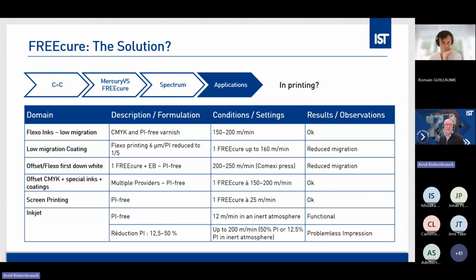But basically, we found that when we use an inerted atmosphere and reduce the photoinitiator content, which is pretty high in inkjet formulations, to 50%, we were able to print almost every inkjet ink in the market with satisfactory results with only half of the initiators. And that has been just the beginning. In reformulating and using additional mechanisms like an amine modification, our partners have been able to reduce the photoinitiator content down to 12% and even lower. And that is a pretty good achievement for inkjet technology.